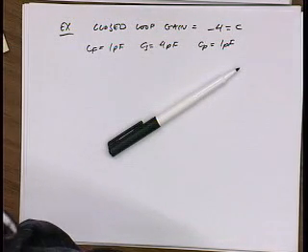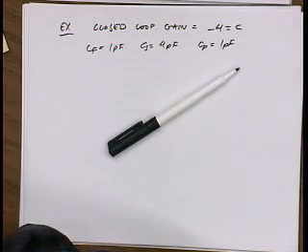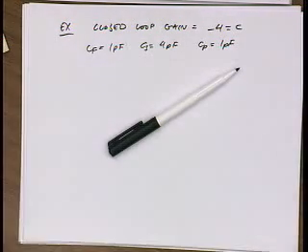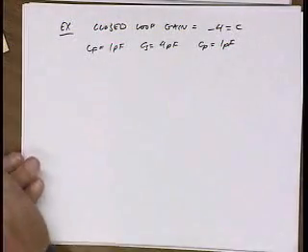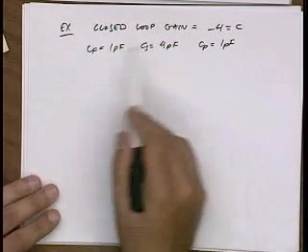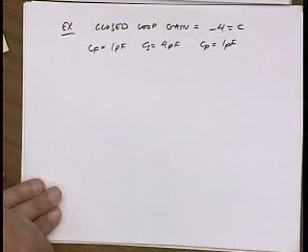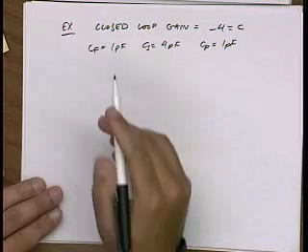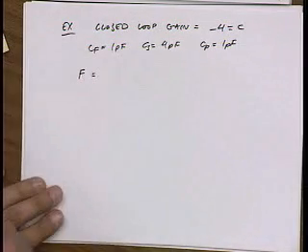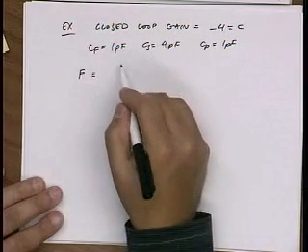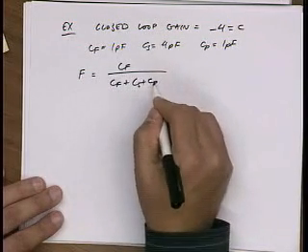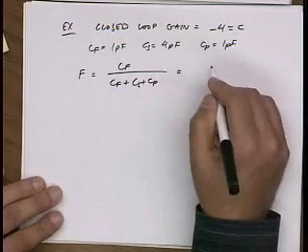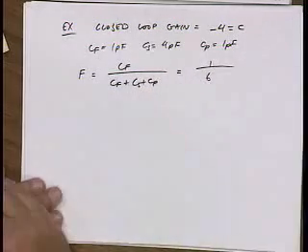Is this arbitrary? Why not use tiny, tiny capacitors? Well, think about what you've learned. Don't think about something you haven't learned yet. How do you determine how to size capacitors? Noise, right? You all know this. So noise determines how we size these capacitors. Let's say in this system, this is the level of capacitance I need to meet the noise specs. Now I calculate this factor F, which we've defined as CF over the total capacitance, so it's equal to 1 over 6.